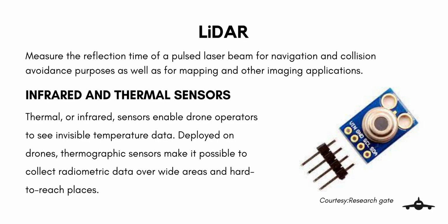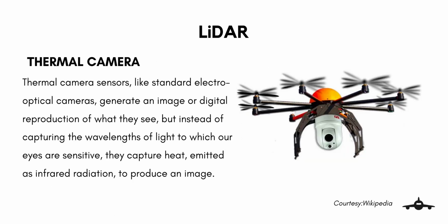Infrared is not visible to the human eye, but one can sometimes feel it as radiated heat when its intensity is high. A thermal camera can hence detect areas of high temperatures. It can reveal overheating sections of electrical equipment in various devices such as switchgears and substations. A drone can help to detect these sections from a distance and increase the safety of human personnel. They can also be used for night vision and surveillance.